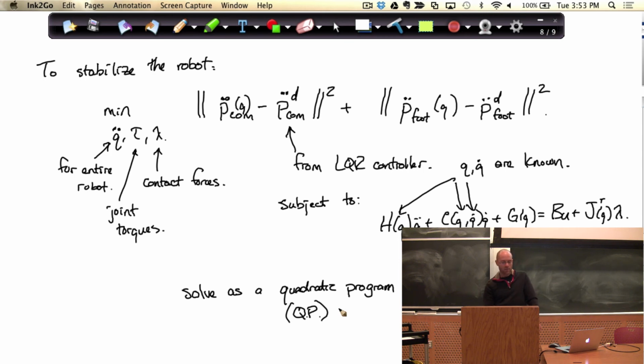So again, we're still thinking about this as LQR planning for the center of mass, and then another optimization that makes it feasible and executes it on the real robot. And there's yet another optimization, which is that inverse kinematics optimization. The LQR part assumes you just command acceleration of the center of mass, and then you figure out how to do that with a static optimization. Yes, that's the current recipe.